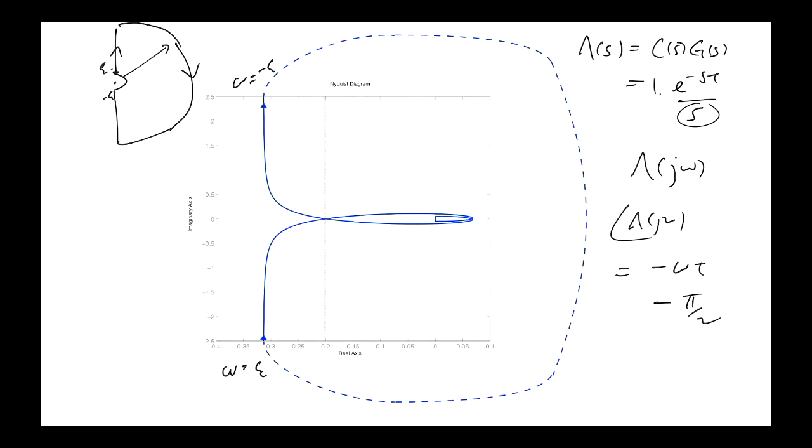Right, so this is just an exercise, if you like, to show you how to use Nyquist plots. That's all I'm trying to explain here. But it suggests that you can stabilise the system with just a proportional gain controller, if closed loop stability is the only thing you care about. Of course, we care about more than just closed loop stability. But from the perspective of closed loop stability, you can stabilise this system with just a constant gain controller.